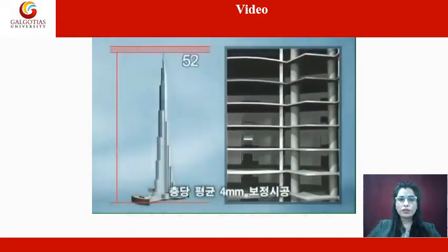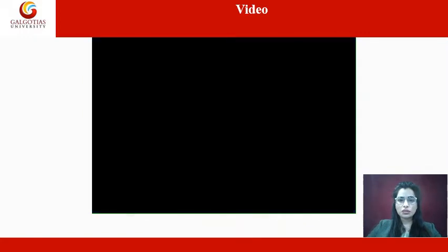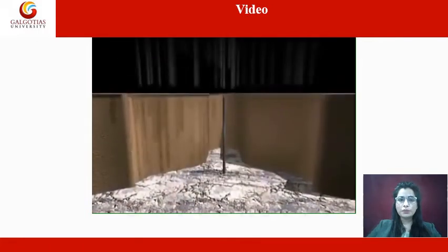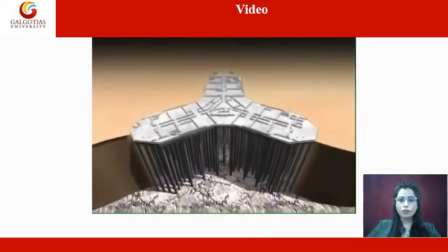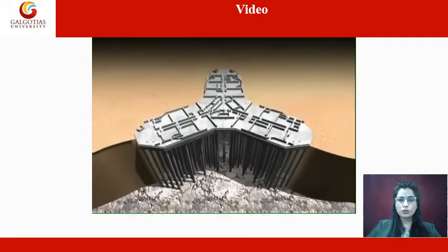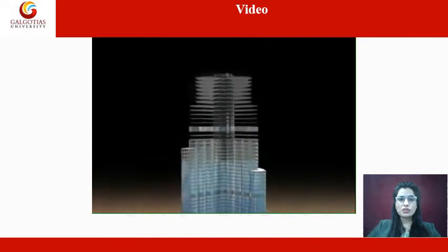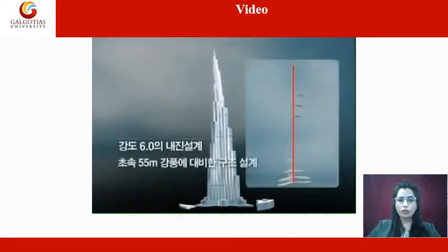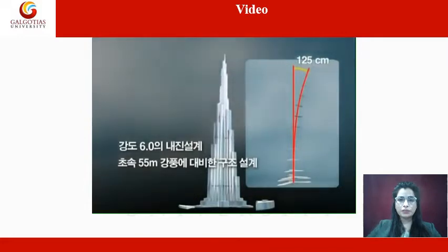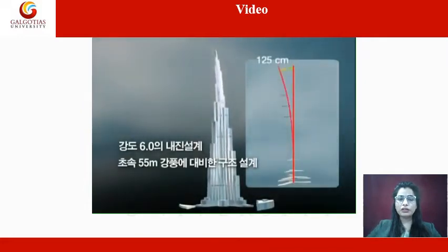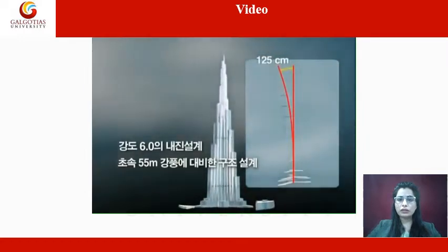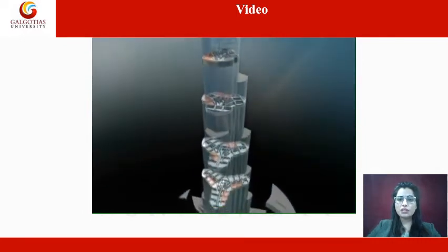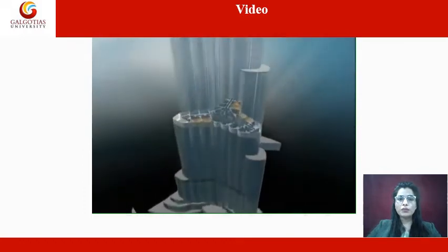It has a 160-plus story tower, with an adjacent podium structure, a 6-story office and a 2-story pool facility. The Burj Khalifa employs a Y-shaped floor plan. Its structural system can be called the buttress core system. The whole system is constructed using high performance concrete walls. The superstructure is supported over a large reinforced concrete raft, which is supported by bored reinforced concrete piles. The raft has a thickness of 3.7 meter and was constructed in 4 separate pours.